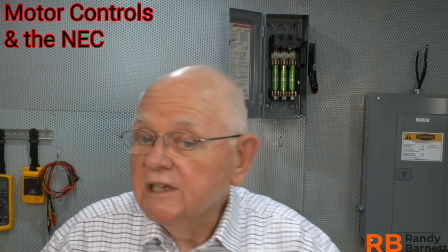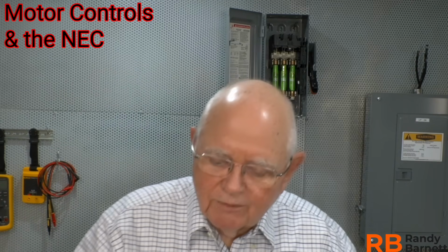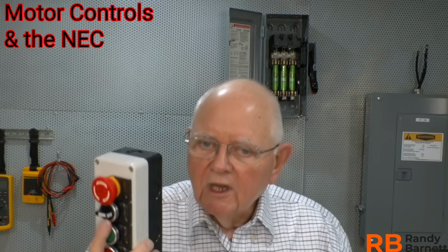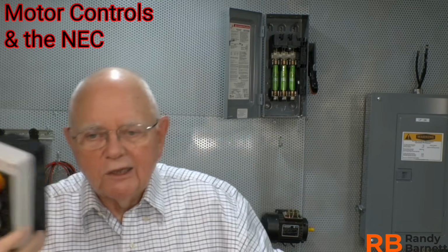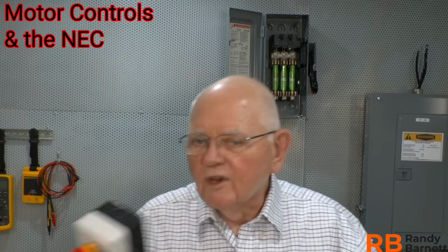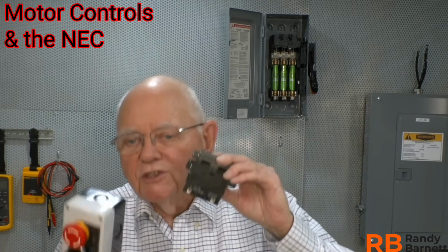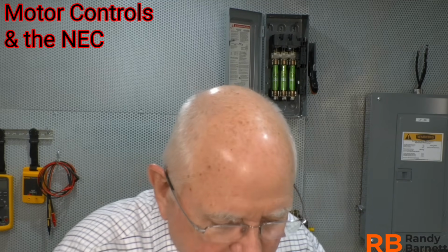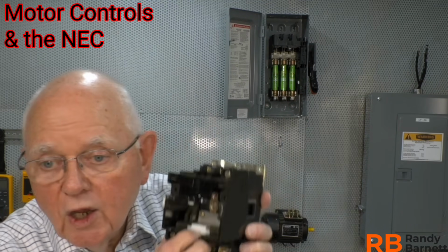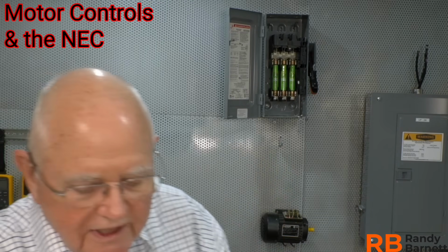Well, I have to look in the NEC, right? And where am I going to look? Well, it depends. What is the power supply to my control circuit? What's going to go through all my push buttons and stop buttons and selector switches and limit switches and sensors and float switches, whatever I got out there in the field? What voltage is going to be applied to those and force current flow through those to this coil of wire to energize that coil and cause these contacts to close? Now, when that coil is energized, it pulls up on this little lever and closes the contacts.